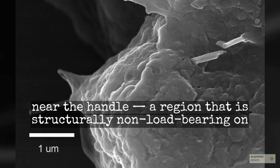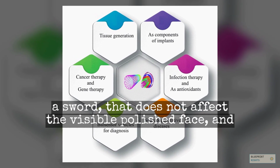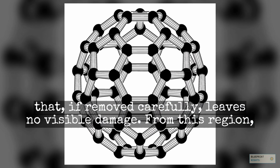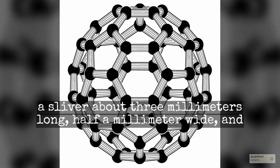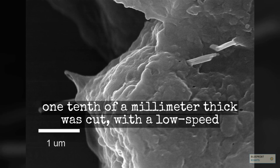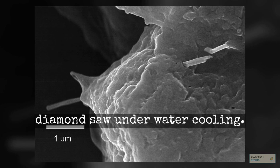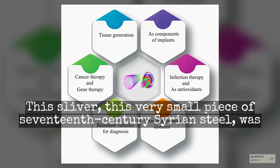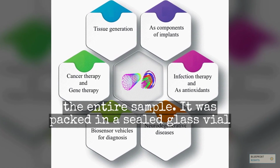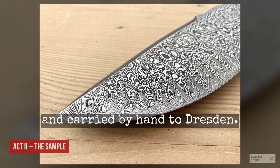The museum's metallurgical curator selected a region near the handle, a region that is structurally non-load-bearing on a sword, that does not affect the visible polished face, and that, if removed carefully, leaves no visible damage. From this region, a sliver about 3 millimeters long, 0.5 millimeter wide, and 1/10 of a millimeter thick was cut, with a low-speed diamond saw with underwater cooling. This sliver, this very small piece of 17th century Syrian steel, was the entire sample. It was packed in a sealed glass vial and carried by hand to Dresden.